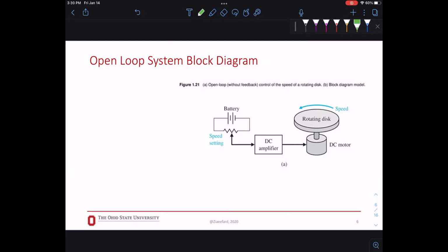So the variable that we feed into our controller is very different from the variable that comes out of the controller and applies to the actuator. Because for the actuator it is the RPM, right? But for your controller, 10 miles per hour doesn't make sense, or 10 RPM doesn't make sense. So a lot of the time we have a battery where we can control voltage, and every voltage will mean something for our motor, right? So usually we control with PWM. Think about it: your control input is not always the same as what actually goes to your actuator. That's why your controller is there. It converts the signal to something that's usable.